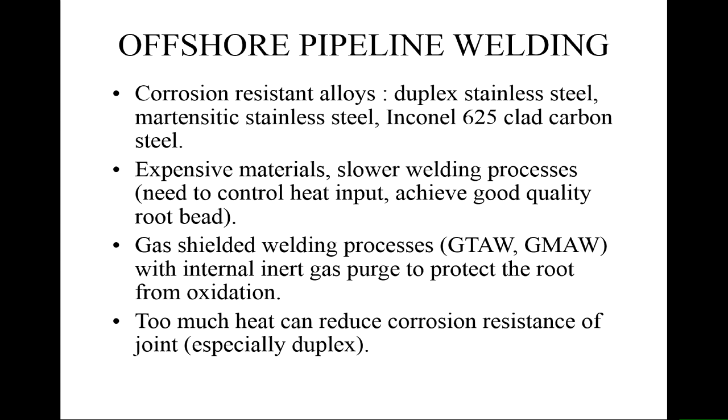When you go away from plain carbon steels or carbon manganese steels, the welding is more expensive and more time consuming. So people try to minimise the use of these corrosion resistant alloys in the pipes where possible. So you might have a riser which has corrosion resistant alloy to some handling platform, and then you might do something on that handling platform, and then the main pipeline to land is just a carbon steel process. It just depends on what the analysis for the field actually is.